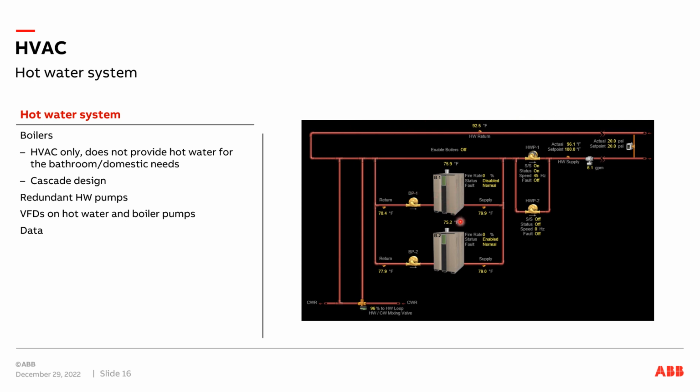So there are some neat energy savings things we're doing here. These two boilers are talking to each other. It's what's called cascade mode. So they know what's more efficient: to run one at a really hot firing rate, or if I need to run two of them at a medium level. They know where all those energy saving points are and when they should run one versus two. It also gives me some redundancy.